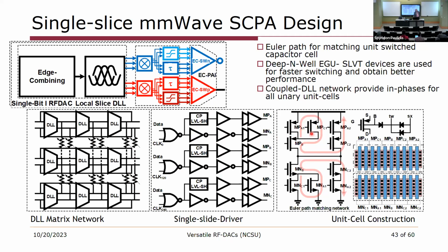And that's why we tried to do this Euler path where we showed that we could reduce one transistor, compact the design just a little bit. As I mentioned, this results in an odd beat frequency every 3 cycles because it's very difficult to balance the resistance of this single PMOS transistor and single NMOS transistor. It would have been much better to just have fully parallel paths and suffer the area penalty.